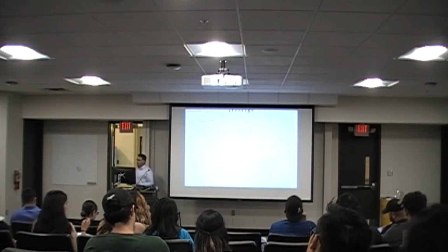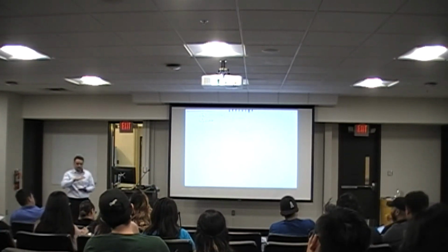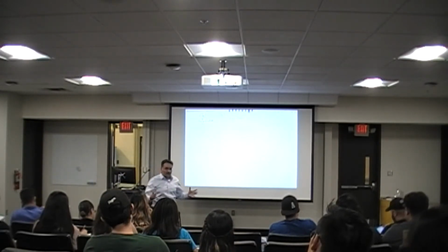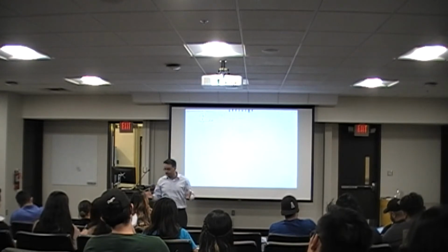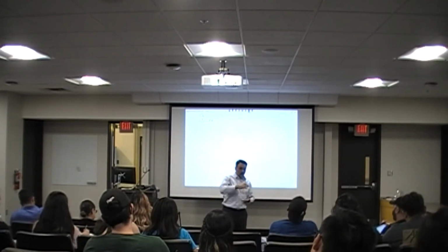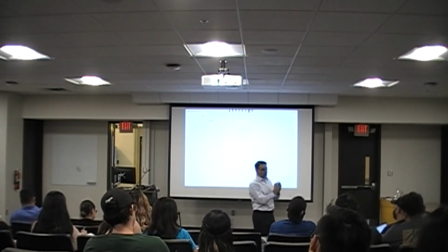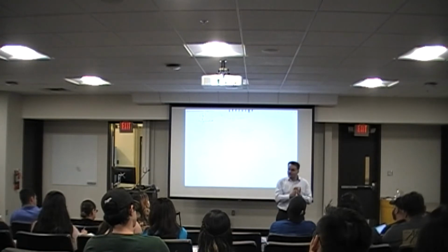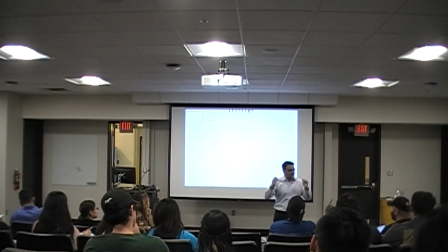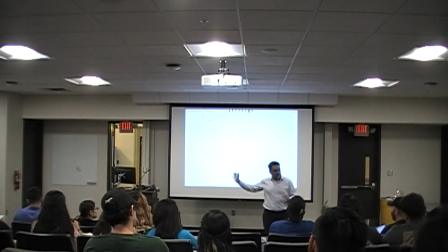All right. Now, what happens if I apply pressure at the top of the soil that is fully saturated? The magnitude of the stresses increases, right? We talked about the stress transference plots. Remember what the stress transference plots were? You apply the load, immediately you see an uptick of pore water pressure, and then with time, you see that the water drains from the medium, and therefore settlement takes place, right? So that's exactly what this equation means.